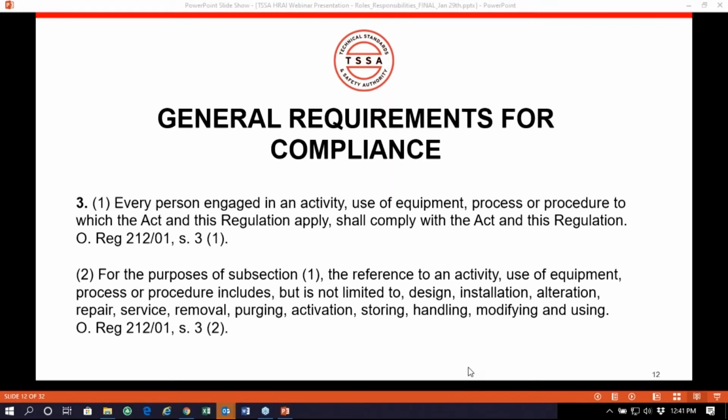And so, for example, a couple of the common ones that I see come across my desk is clearance to rooftop equipment. Very often we run into situations where the equipment's much closer to the edge than 6 feet required by the code, and so we need to demonstrate equivalency and safety. So generally they'll apply to have guardrails put up to protect the technicians who happen to be working on the roof.